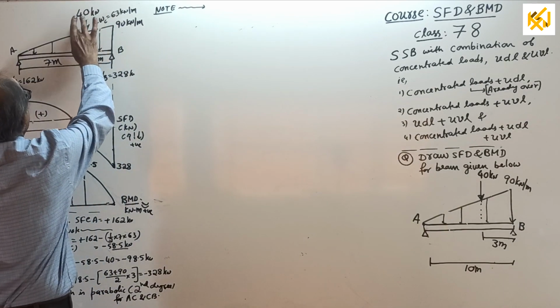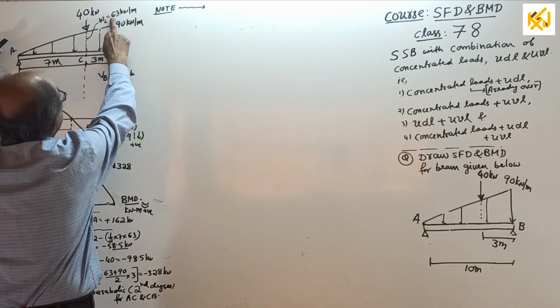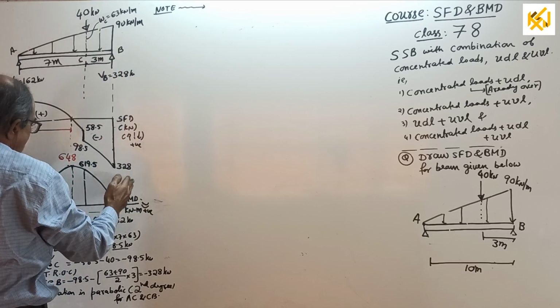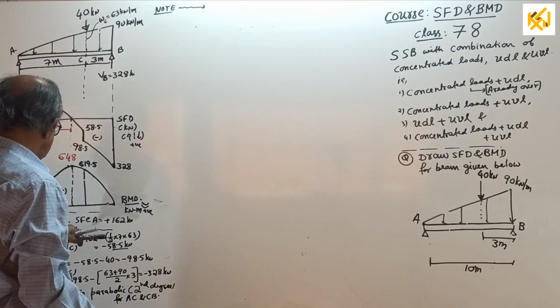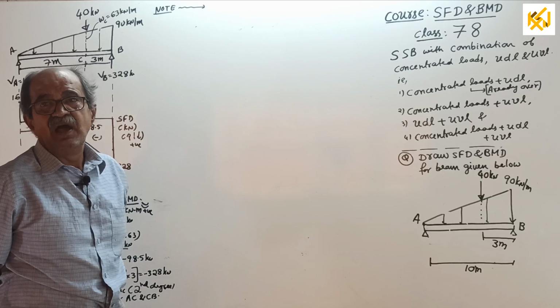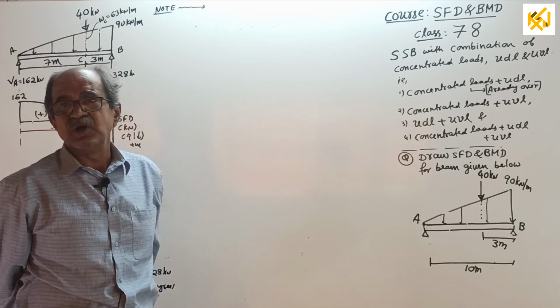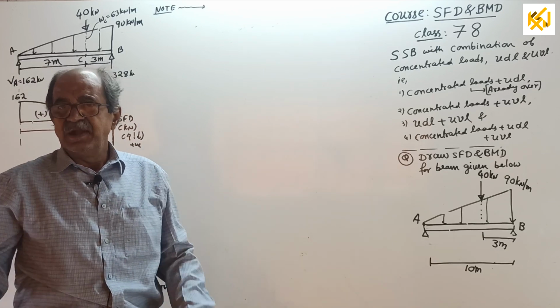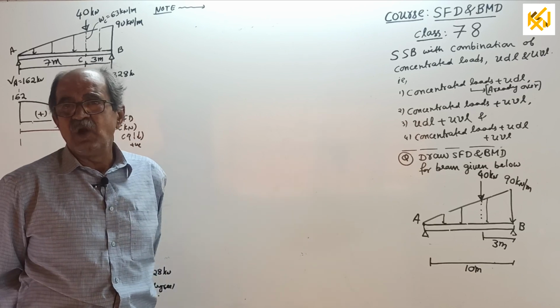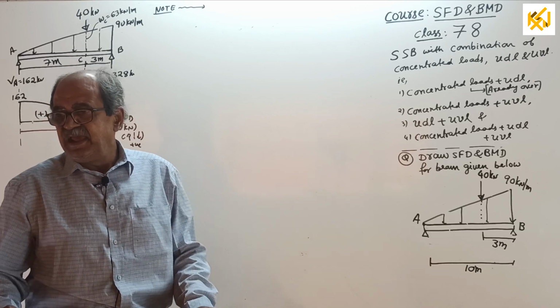Write a neat sketch of the beam here, somewhat to scale. I entered that 63, reactions over. Draw SFD BMD. I will do one thing now. The shear force calculations I told are done for academic purposes or to make a complete solution. You can draw the SFD without writing any calculation.